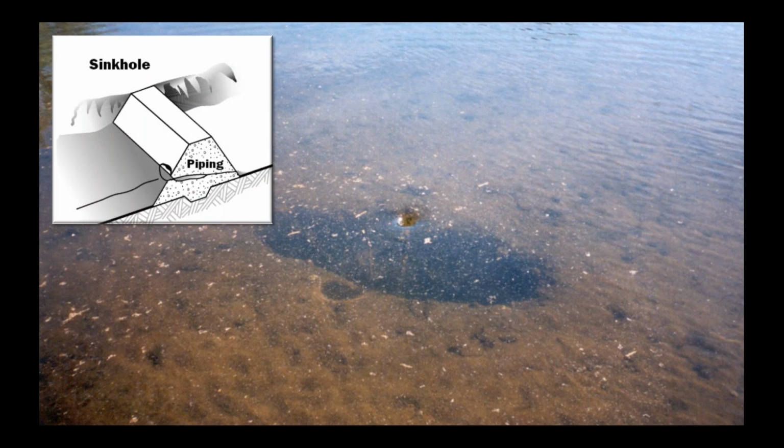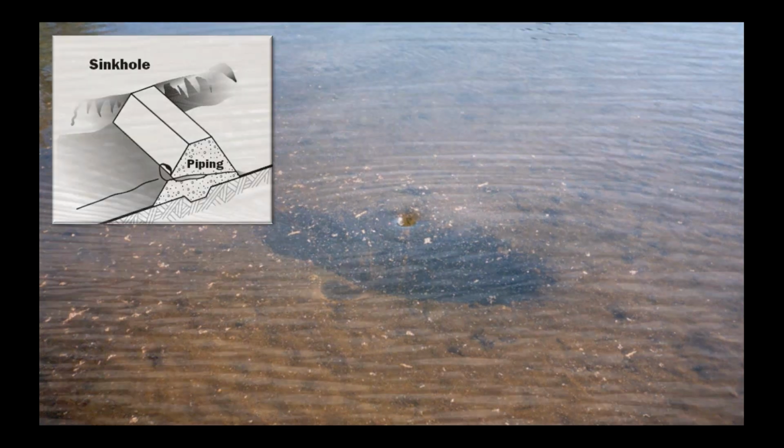Another thing to look for when inspecting the embankment and looking at seepage type failure modes is sometimes you get so focused on the embankment that you don't look at what's going on in the reservoir. And right along the shoreline is a real important place to take your time and to observe and actually look into the reservoir to see if there's any evidence of seepage. So here, for example, we see a little vortex, and there's a sinkhole developing right below the water line on the upstream side of the dam.